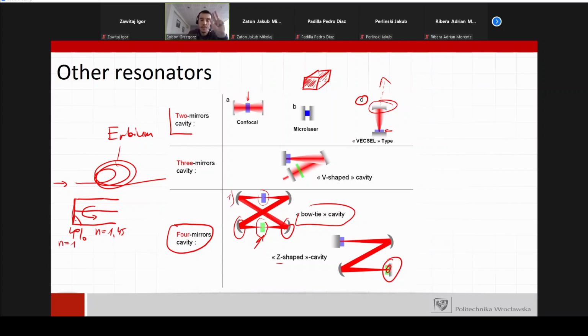So we have something like unmatched impedance in electronics, right? So you will have reflections if you don't have impedance matching. And the same applies to optics. So if the light travels from a large index to a low index, we will see that there is some reflection. So it might happen that if you just have a bare fiber without any mirrors, you will have 4% of reflection from both ends, and this is enough for a laser. So we can build a laser which doesn't have any physical mirrors, but there is a parasitic mirror because of this 4% of reflection.